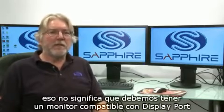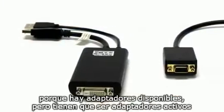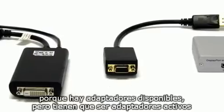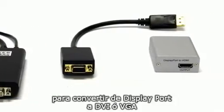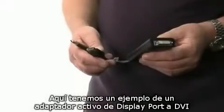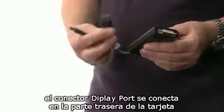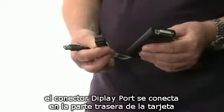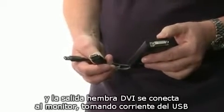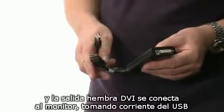Now that doesn't necessarily mean that it has to be a DisplayPort compatible monitor, because there are adapters available, but they have to be an active adapter to convert the signals from DisplayPort to either DVI or VGA. So here's an example of an active DisplayPort to DVI adapter. The DisplayPort connector goes straight in the back of the card, takes a female DVI standard cable to the monitor and is powered by a USB connection.